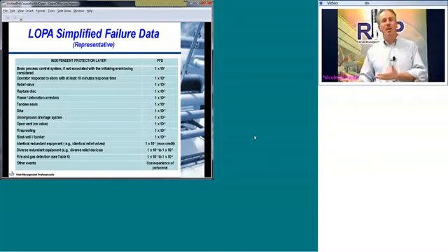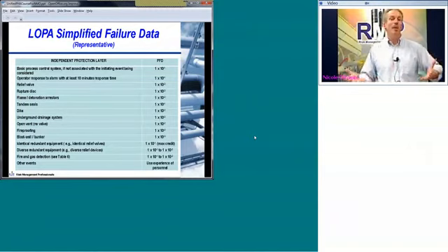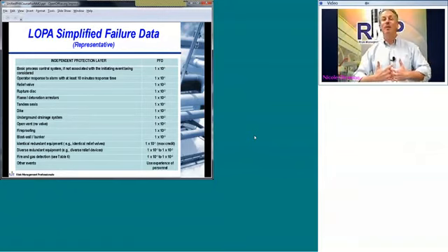The population that generated the data may have different manufacturers, different operating conditions, clean or dirty service. There can be a lot of differences. And also reporting: have they reported all the failures? Have they accurately binned what types of failures they are? All those lead to uncertainties in the accuracy of the information as it applies to your equipment and your plant site.